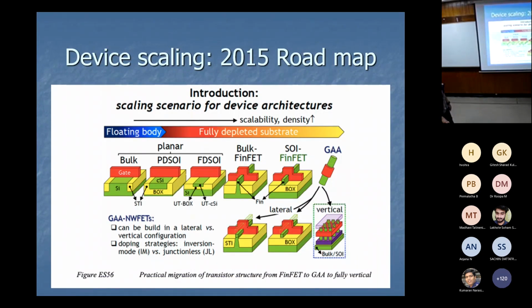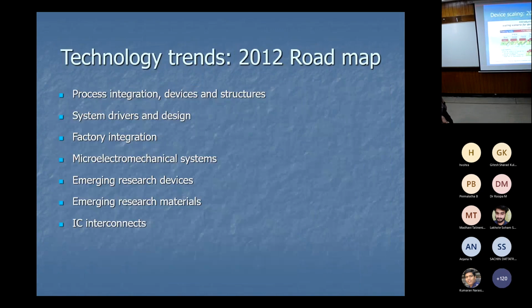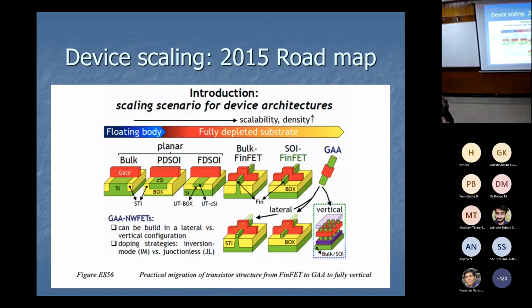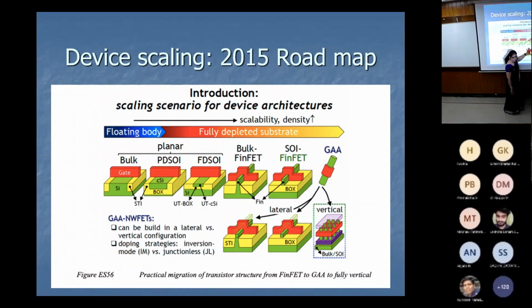Yeah, again, various device structures. I'm sure all of you are aware of these device structures: gate-all-around, and there are various varieties of FinFETs, and again, 3D structures are all available today for system integration. And one point to note here is we traverse from planar or lateral devices to now vertical stack structures. That's the trend we are seeing even in the device structures, right? We are stacking even at the device layers, to still continue to take advantage of scaling.